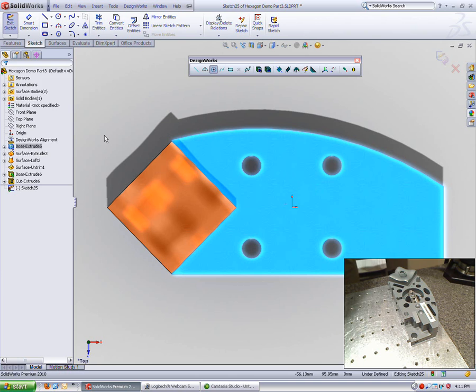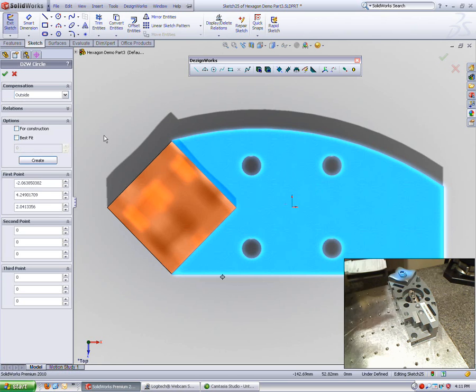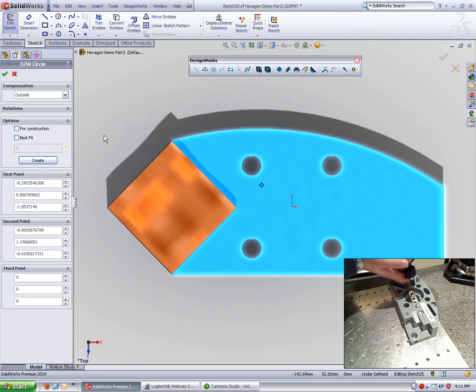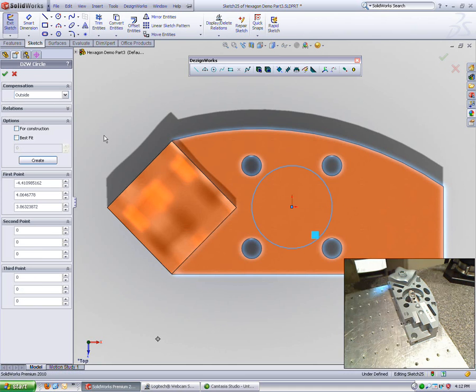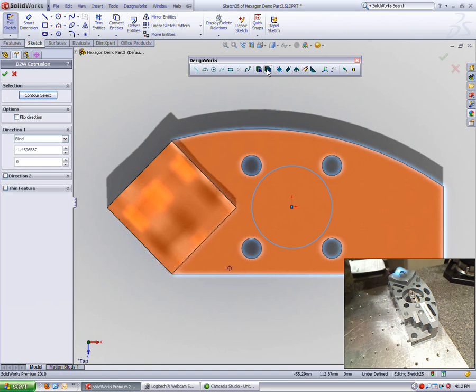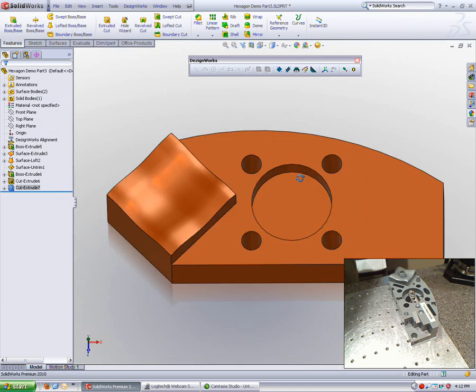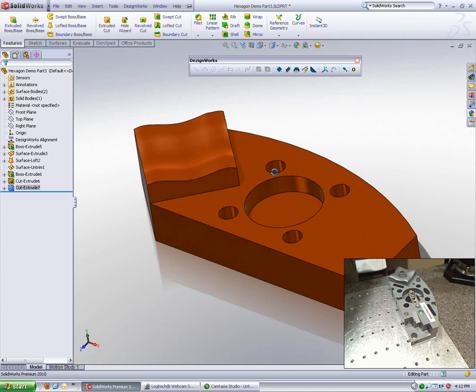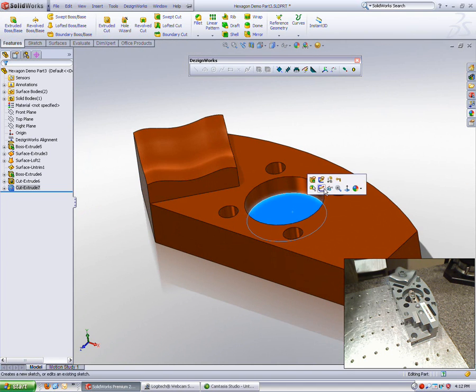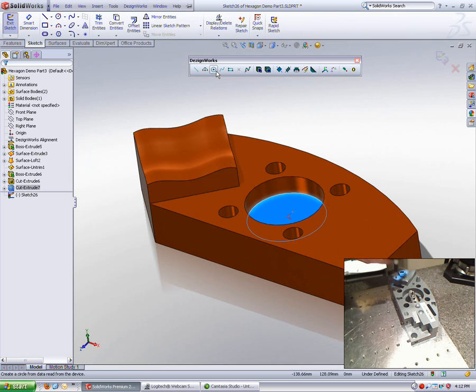Now again, we'll also do the same way for the center circle. We can do 3 points to do circles. We can also do a best fit circle. Here we're doing 3 points again. You see the compensation for the size of the ball probe, and we'll now use a Dezignworks cut and go down to that inside surface which we just picked with the probe. We'll do another quick cut to finish that off,